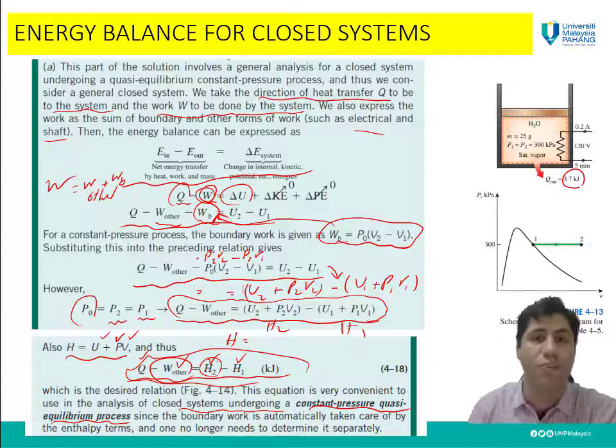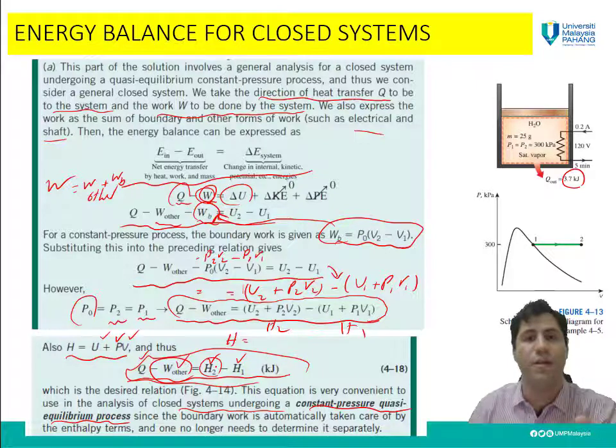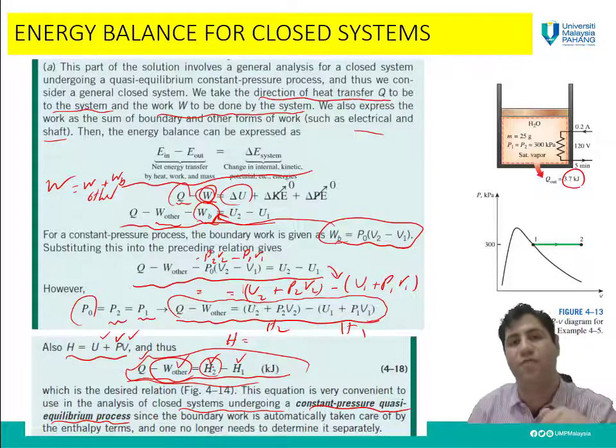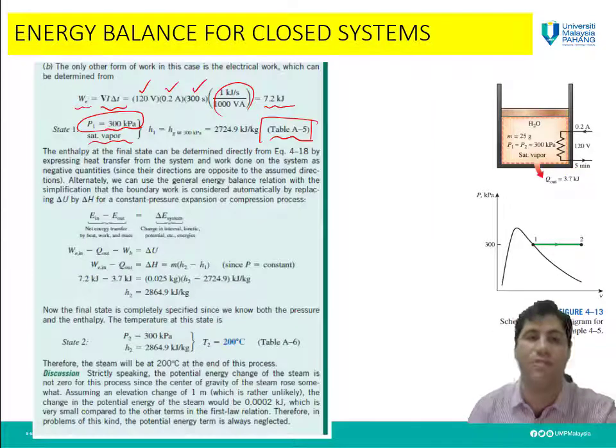If we have H2 as the enthalpy of the system, we have pressure as well. So we have P2, then we will have H2 as well. We have P2 and H2 for steam. We need to go to the table related to that steam at that pressure and that enthalpy, and we can find the temperature for that state from the table.